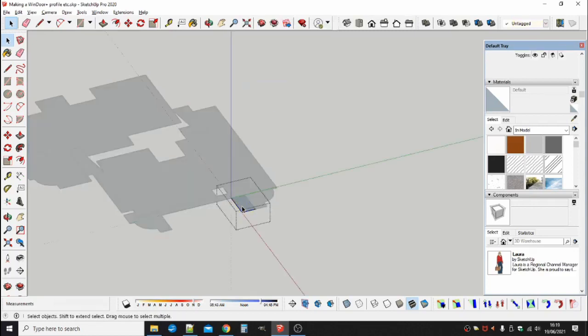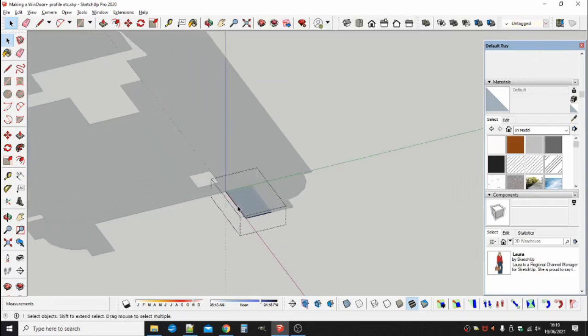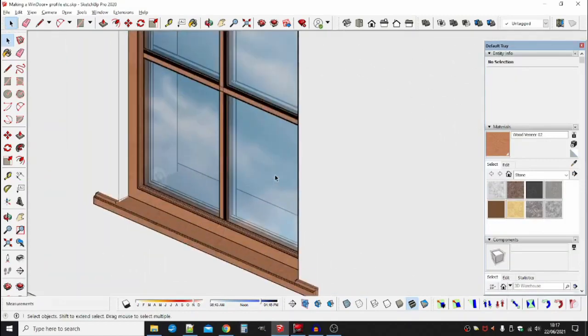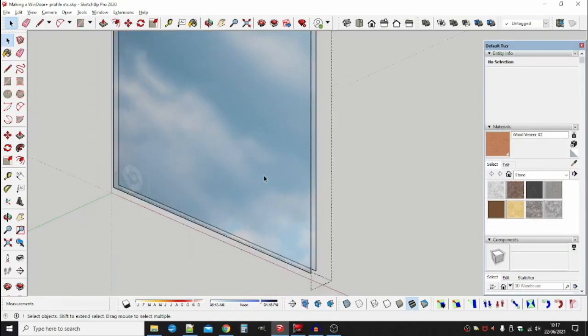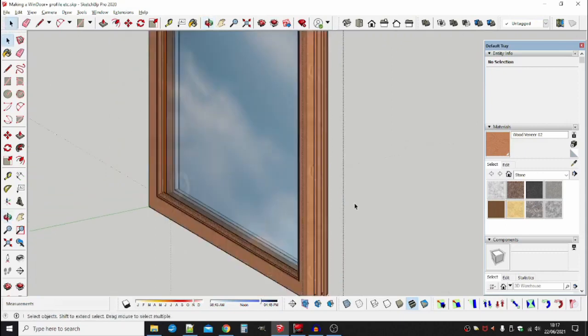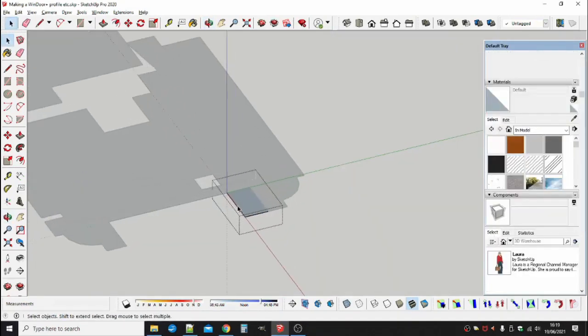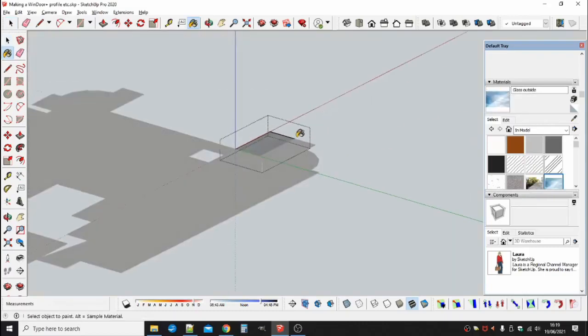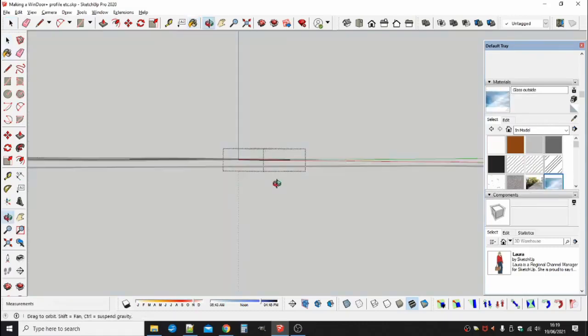Note that WinDoor plus Custom Profile does not show the individual sheets of glass in a glazing unit. WinDoor plus Custom Profile represents glazing units as two simple glass faces, the inside and outside faces of the unit. In the profile, the glass sheets of the glazing unit are SketchUp groups rather than faces and edges. Each glass sheet is represented by a single rectangular face in a single SketchUp group.